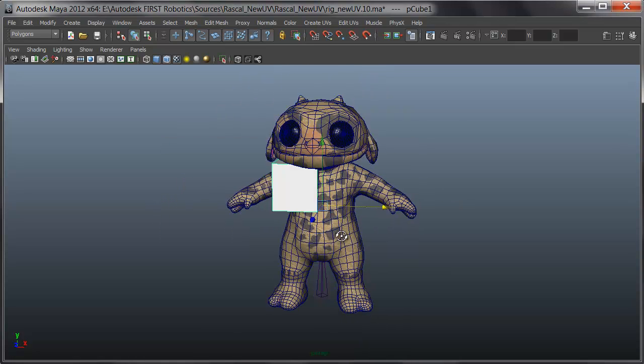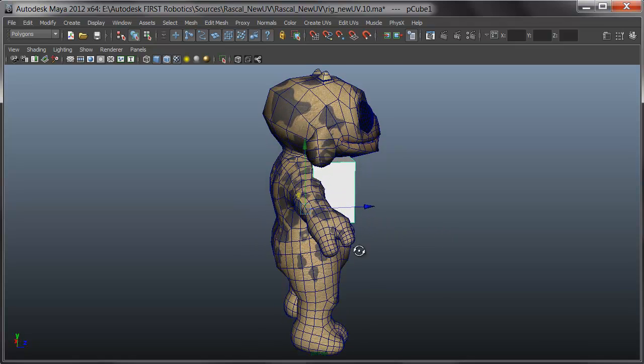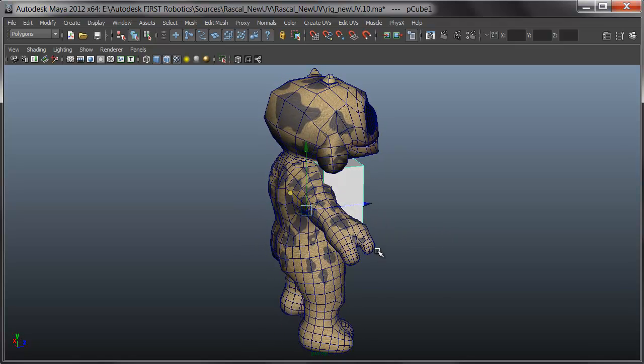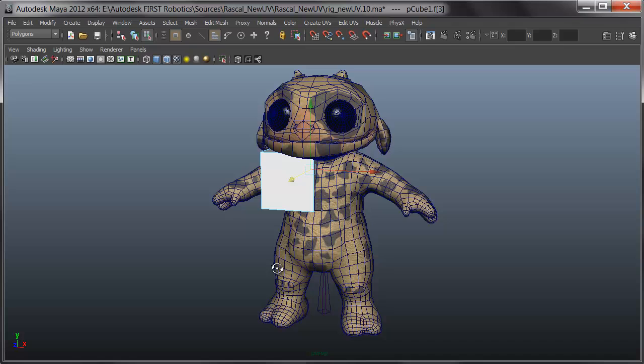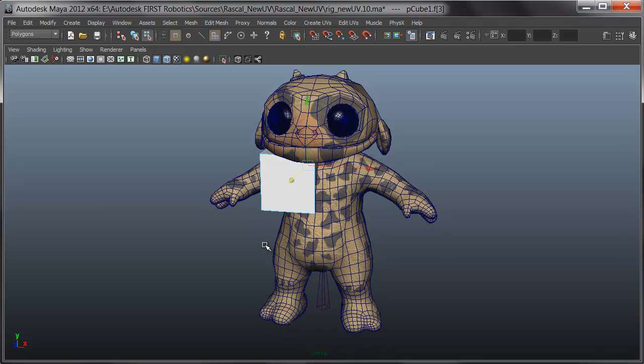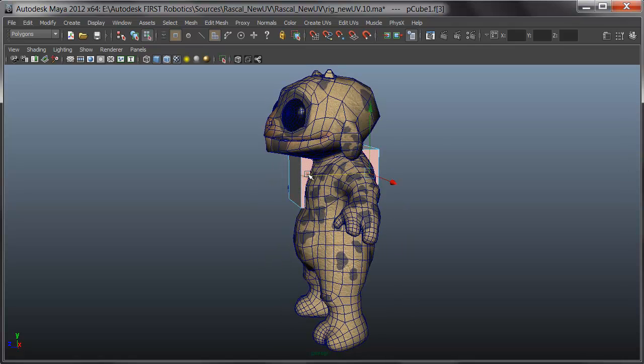I'll use my hotbox to go into a perspective and just make sure the box is roughly in the right position. Looks like I need to take the back polygon back so the shirt will fit over him decently. Now it's ready for a proxy. What I want to do for a subdiv proxy is delete the center face of this box, opening up the structure.